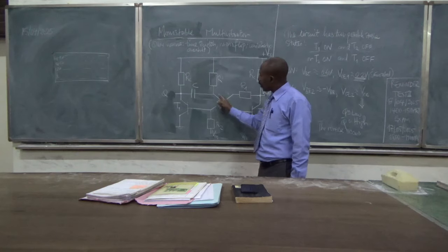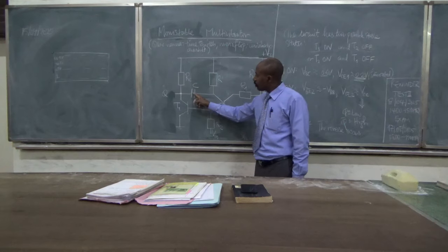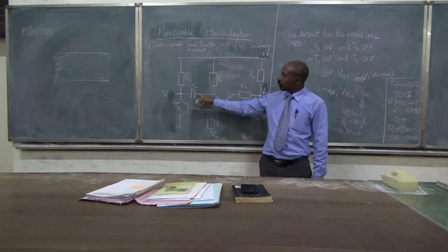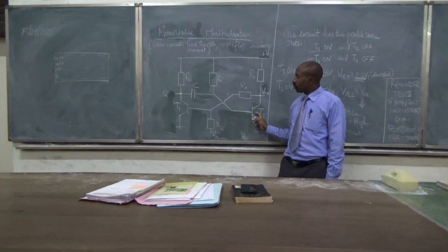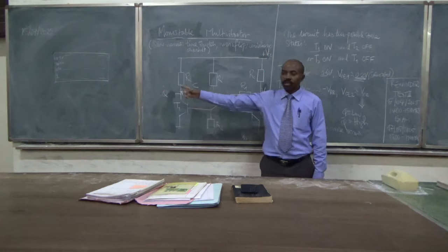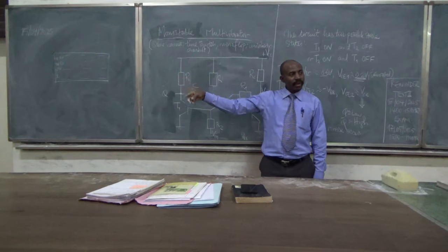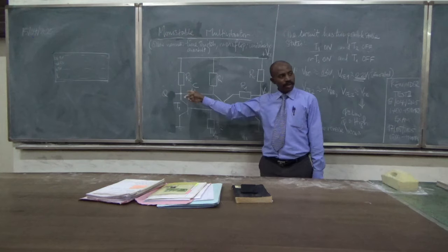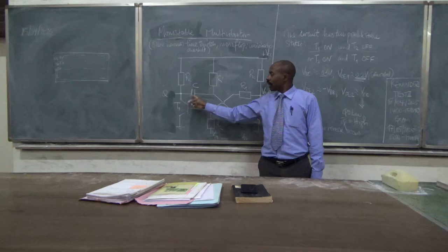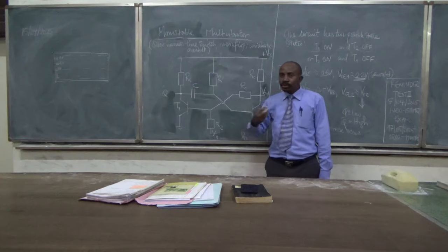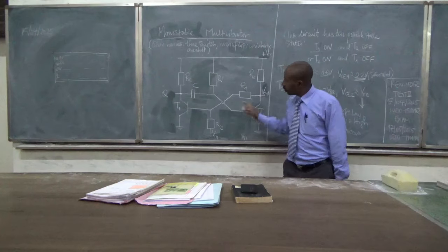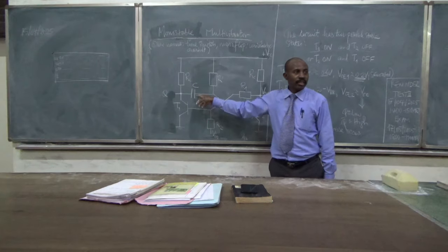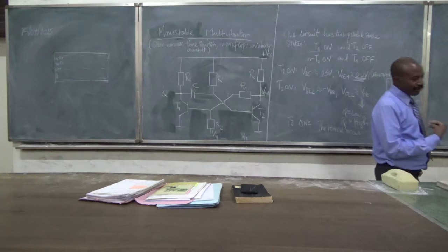With this current here, we have a chance of having the charge stored here being the one to trigger this transistor. But this one is just biasing that part to allow the current to go here to charge this other capacitor. But the one where you really get something being seen will be when you have this capacitor releasing what it will have stored.